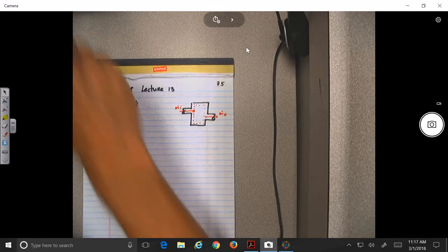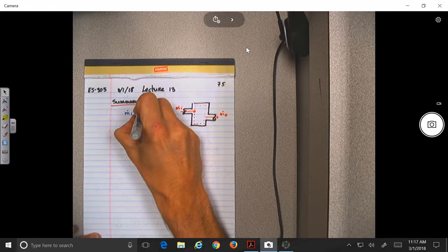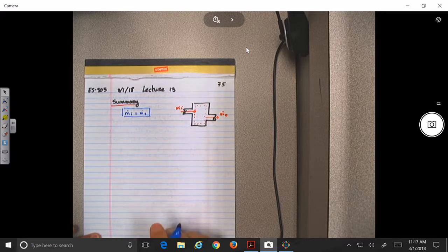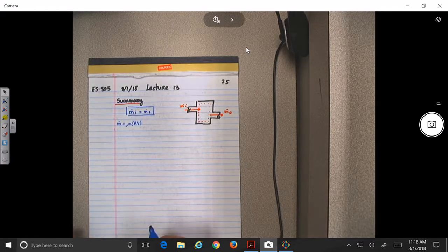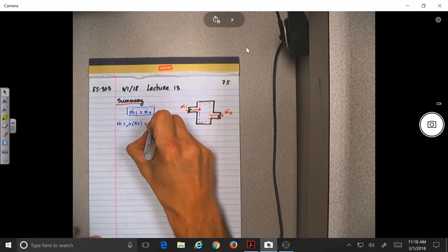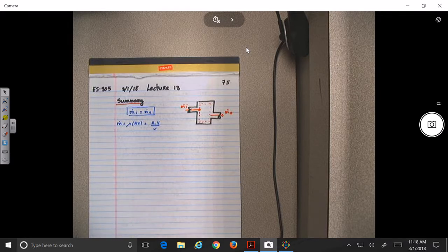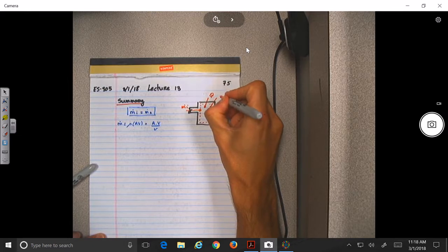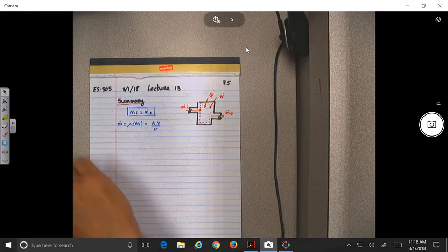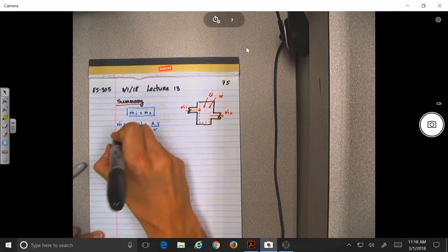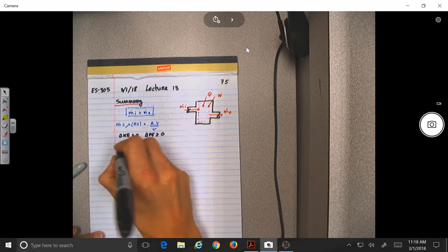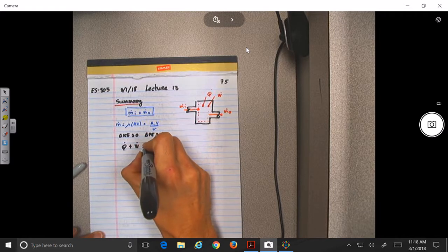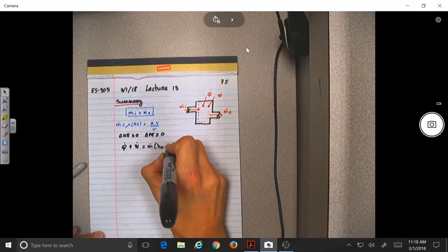Because of conservation of mass, the total mass coming in needs to be equal to the amount of mass coming out. The general definition for the mass flow is rho AV, but in thermodynamics it will be more like AV over little v. A is area, V is velocity, little v is specific volume. If we consider heat or work going into that system, and neglecting kinetic and potential energy, we have the equation Q dot plus W dot equals m dot times (h out minus h in).